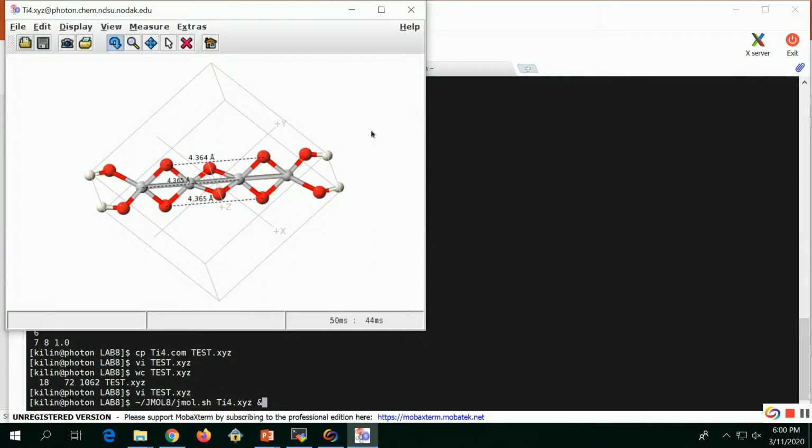A little comment: half of the class use this file, half of the class are using the one borrowed from Mahek. The file from Mahek is better. There will be a little less operations. I will show how to process this one, but those following her file will live an easy life. The difficulty is that we will need to rotate this file by 45 degrees. The one from Mahek is already aligned along one of the axes. The model should be aligned along one of the axes in order to impose periodicity. It is not scientifically mandated, but it is so much easier to set up periodic boundary conditions if the axis of the periodicity coincides with one of the Cartesian axes.